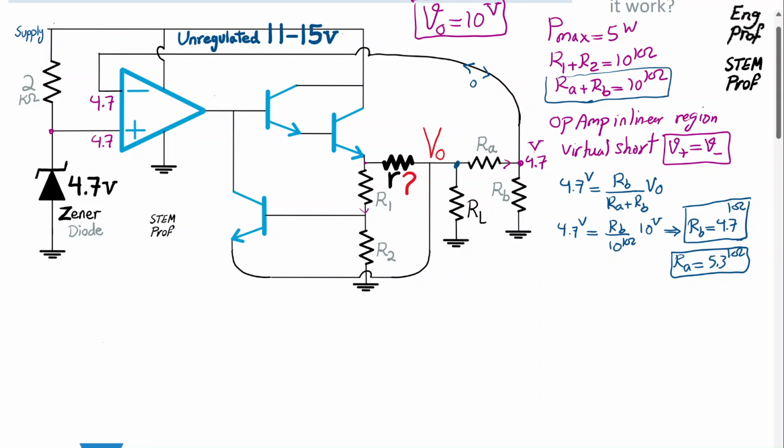Okay, so in normal nominal operation, when the current is being provided by the Darlington pair here, which is the high power pair, especially this transistor, if the current is within the right range, this transistor should be off, and the regulated supply is just providing current to the load like this.